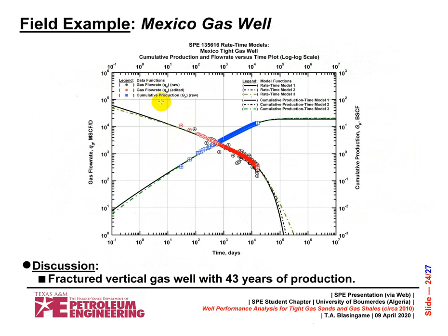And let's see how they compare. So, of course, I wouldn't show it to you unless it worked. But in this particular case, we have the gas rate data and the cumulative production data. Gas rates are on the left axis, cumulative production's on the right. And we fitted Models 1, 2, and 3 through the data. Generally it looks very good through transient flow. Almost everything is perfectly matched. And then we come out of transient flow and we have significant differences in overall extrapolations.